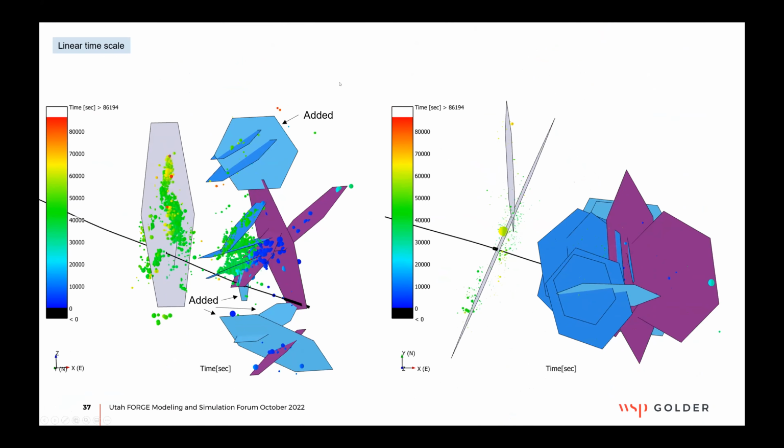Right. Yeah, that's why I will say, Luke, this fracture I added is one of those cases where there's no microseismic data to justify it, but we would expect these orientations. We can go back and check in the stress field, but this probably isn't one that's oriented very well for failing in shear. So this might be just a pre-existing fracture that connects or not. We can add those things, but other than knowing that these orientations exist and might not have a microseismic signal, we don't know where to put them. But I did feel free to add a few, saying I can't justify this, but I'm going to put this in here anyhow to connect things up.